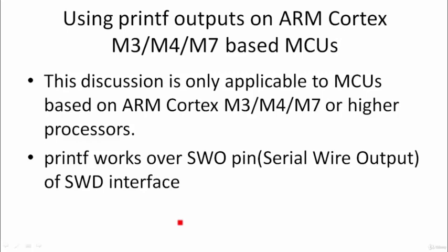In ARM Cortex processors, we can make printf work by using the SWO pin of the SWD interface. SWO stands for serial wire output. Let's explore more on this.